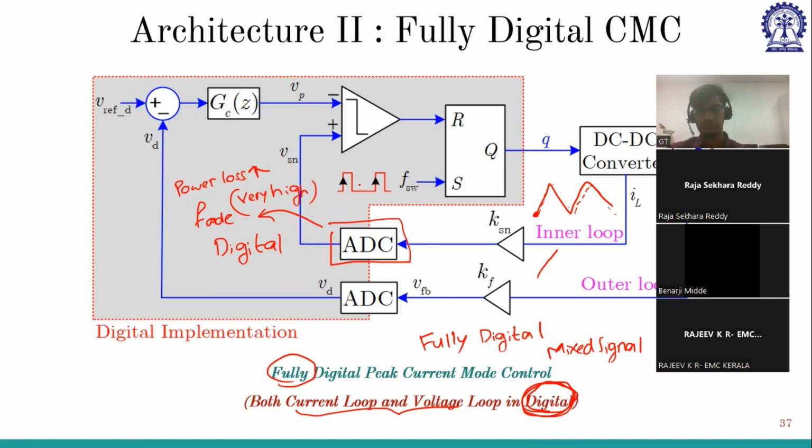And if we can actually take multiple digital control techniques, if you sense the inductor current, we will have so many advantages because now we have the inductor current. We can write different high level algorithms. We can use this inductor current in our control. So we can use this inductor current like a feed forward in the digital. So for different control modulation techniques, it will be used. And many commercial ICs that are coming now, some of them are sensing the inductor currents.